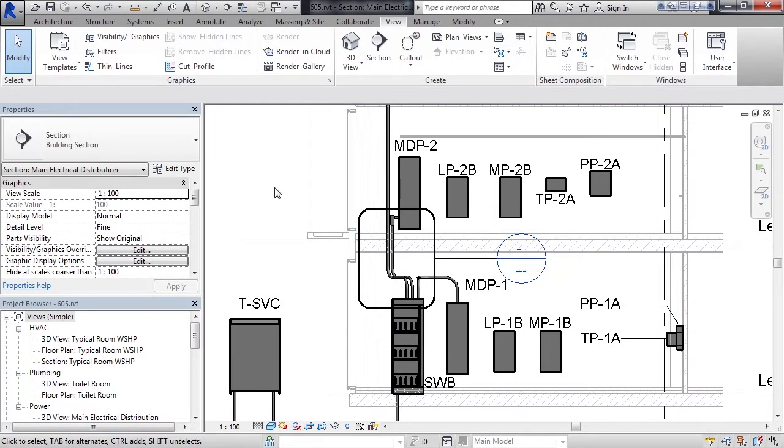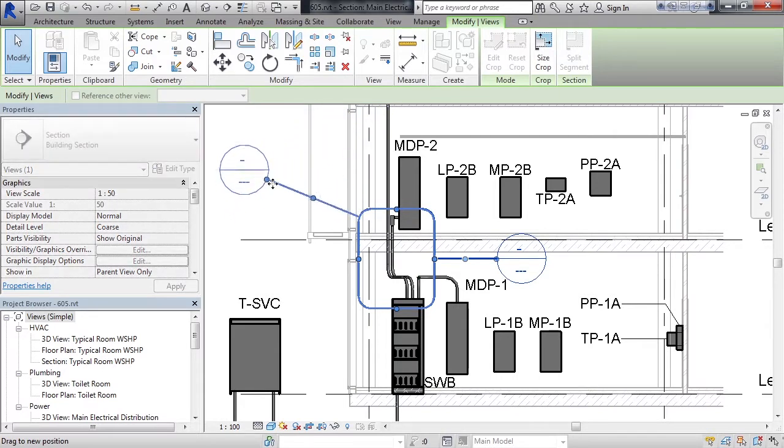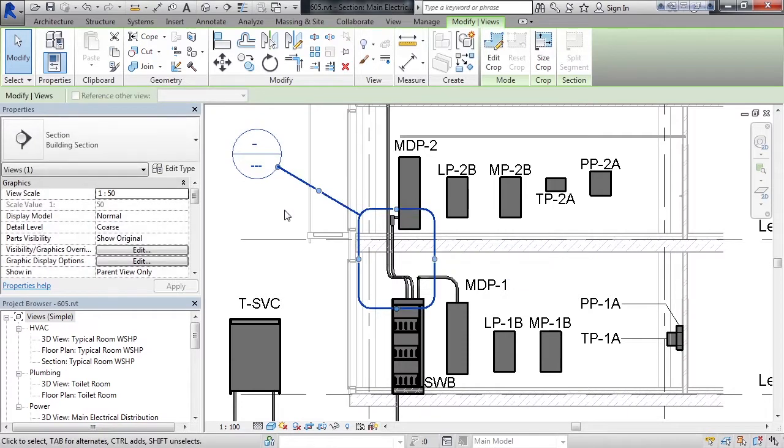Now to move the actual callout symbol, simply click on the callout frame or line connecting the symbol to the callout rectangle, and then you'll see a little circle appear next to the callout. That callout circle can be moved by using the drag handle that's attached to the circle. Just hold your left mouse button down over it and move, and you can drag this callout symbol along with its extension line to a new position and then release it.